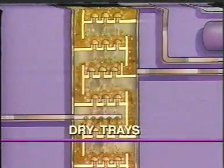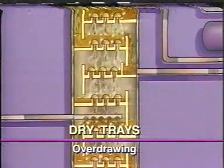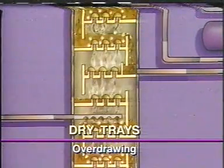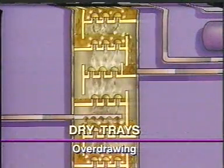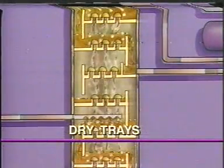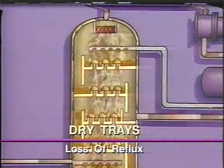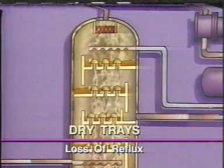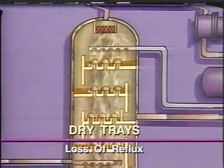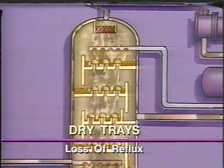Another abnormal operating situation is dry trays. Dry trays sometimes occur because too much liquid is drawn off as side product. When this happens, the trays in a section of the tower immediately below the draw-off point become dry. An interruption in the supply of reflux or insufficient reflux to cool the rising vapors can also cause dry trays. Reflux problems are usually responsible for dry trays at the top of a distillation column.